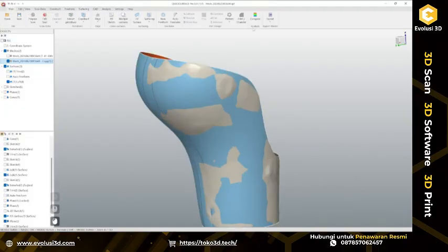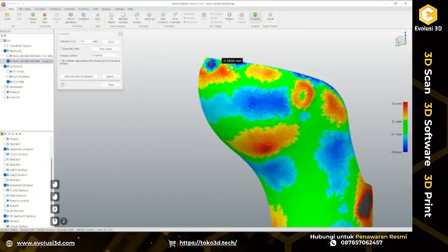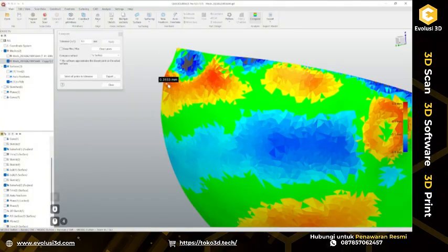If we're looking at the deviation analysis, on the other side we're just 0.3 millimeters away. And this is not a precision part, this is an old part and bad scan data. So probably if we create a part, for example printed from this given surface, 99.99%, no one would ever notice this small difference.